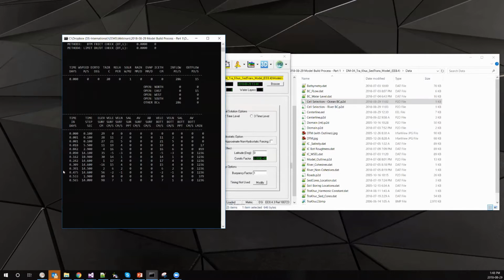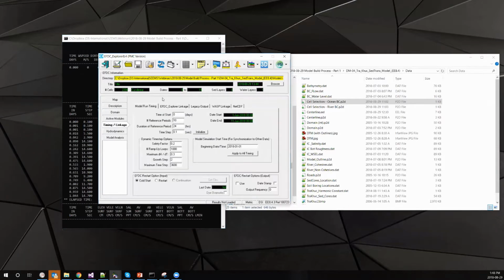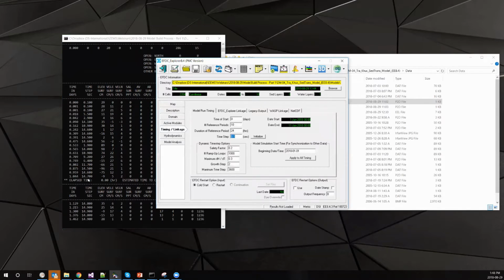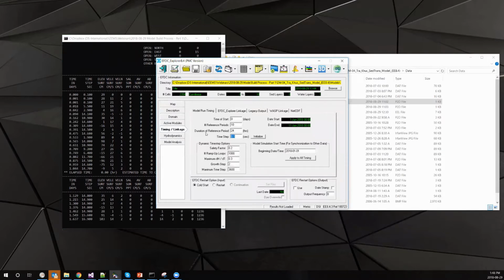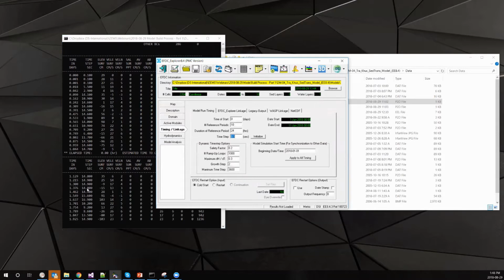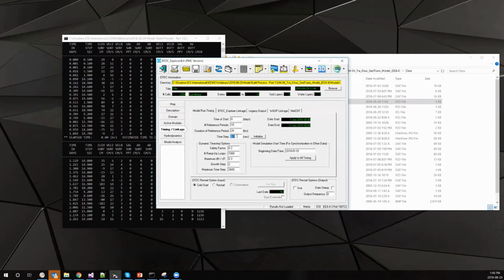You can see here this is the time of day, and this is the actual computed time step. Remember that the time step I specified over here was only 1/10 of a second, but I'm getting up to 14, 15 seconds. The increment between subsequent time steps can't be any smaller than the 0.1.